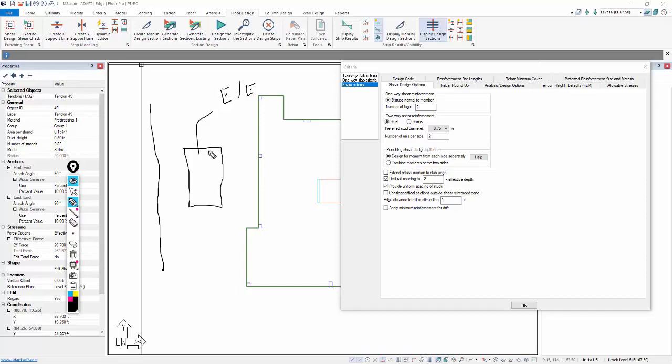So bending about one direction, we're bending maybe parallel to this free edge. Bending the other direction, we're bending normal or perpendicular to the free edge, and that changes the way we calculate the centroid of the critical section and consider the stresses based on the angle or the direction of bending. But this ultimately is a 3-sided critical section.